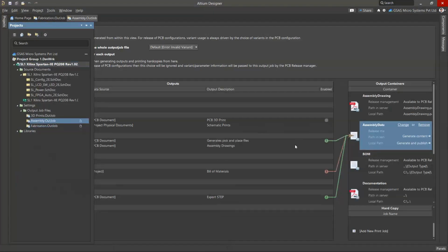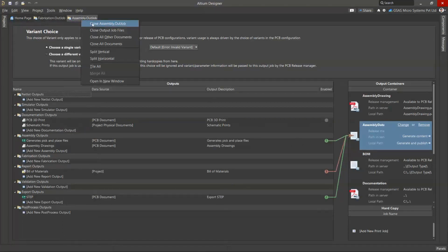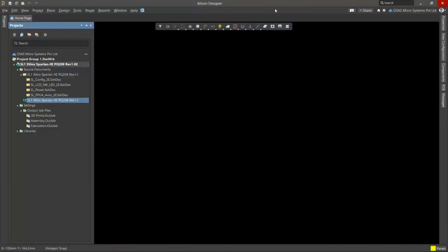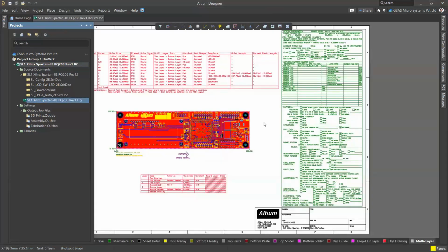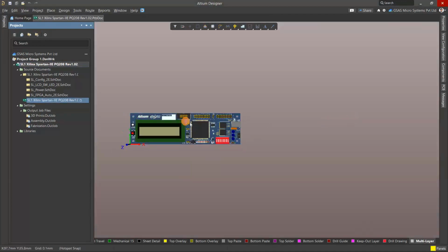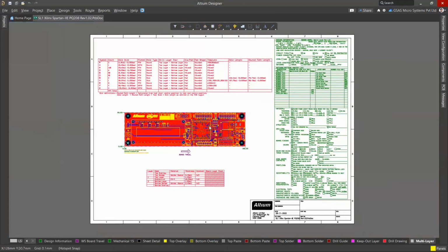This is very important. Or if you don't want to, after project release also you have to configure, but better just configure before you jump into the project releaser. And then once you are done with this, let us see the design file, how it looks, the PCB editor file. So this is the PCB. When you press 3, you are able to visualize the same in 3D. Now I want to release this output data by using project releaser to a local folder in a zip file.